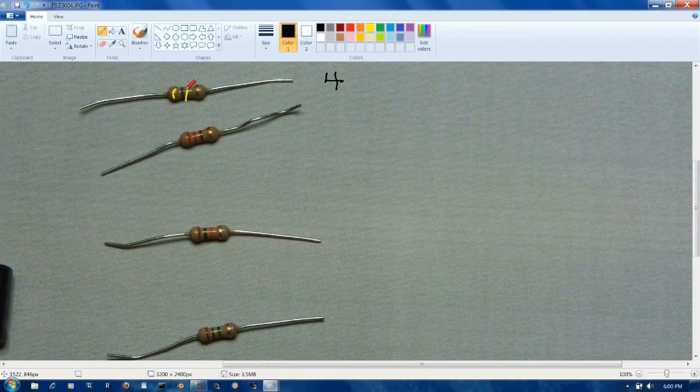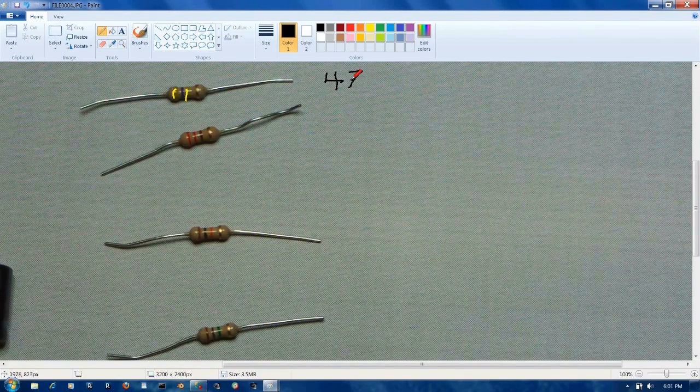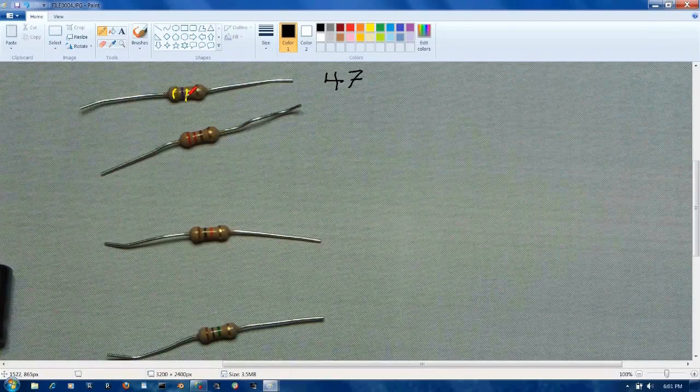So that is 4. Violet. It's not blue, it's violet. Once again, we have black, brown, which is 0, 1, and then red, orange, yellow, green, blue, violet. And that's 7. You can't see me, but my fingers were going up as I went through the colors, and that's how I figured it out. It was 7. And then, of course, we have yellow again.